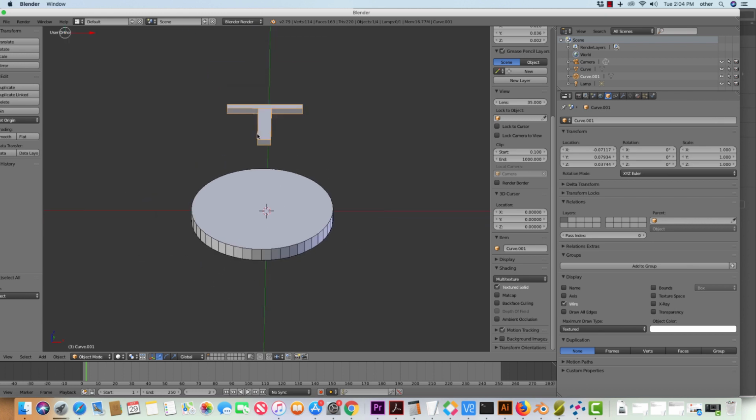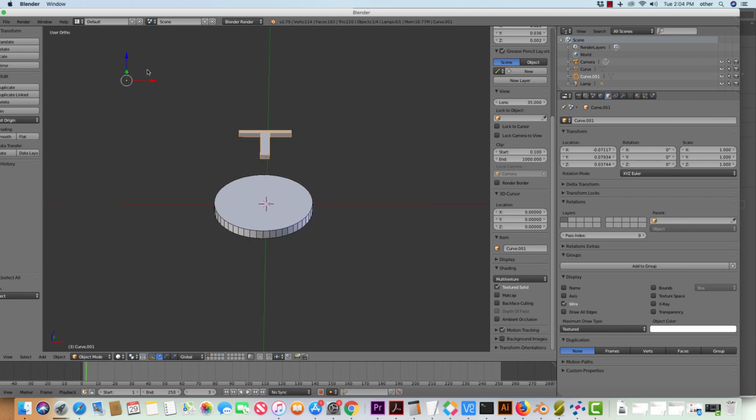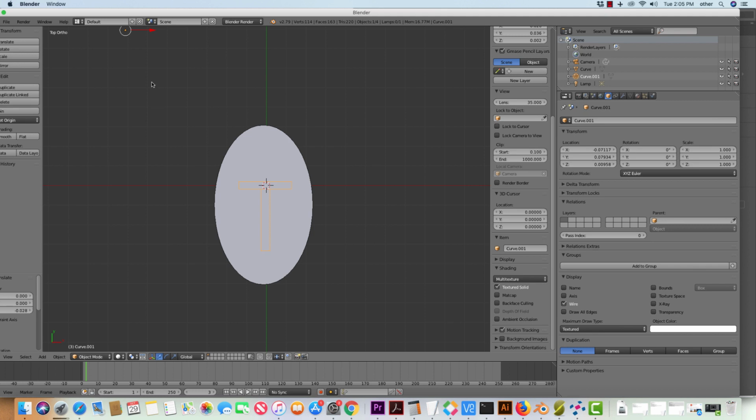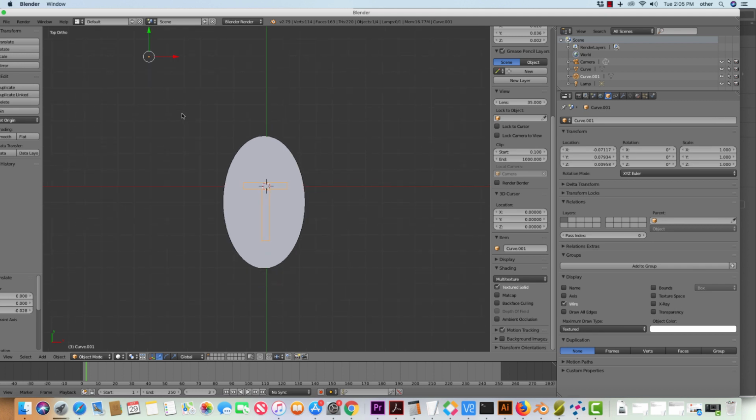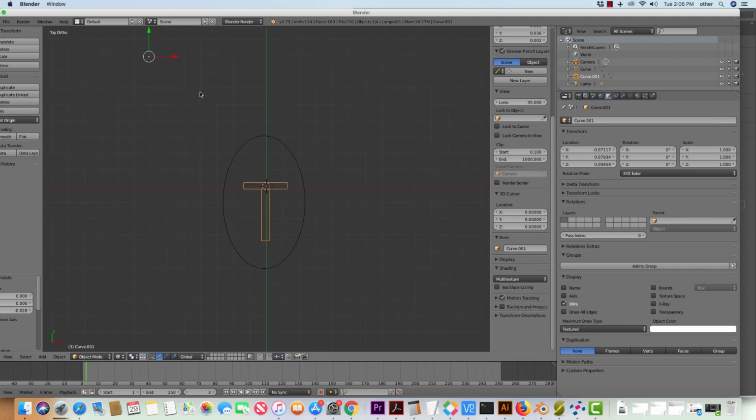And you can move, again, this is the wheel mouse. You can move this one down and you can see that it cuts into the shape. You can see it in that view. You can go to 7 on the keyboard. You can see it in this view. You can hit Z on the keyboard and see it in this view, which is a little easier sometimes to center it. Let's say I want to center this.